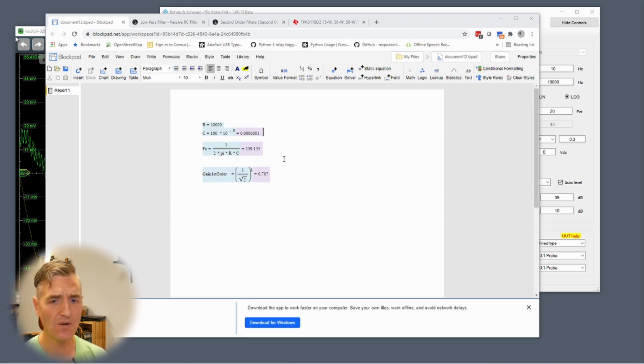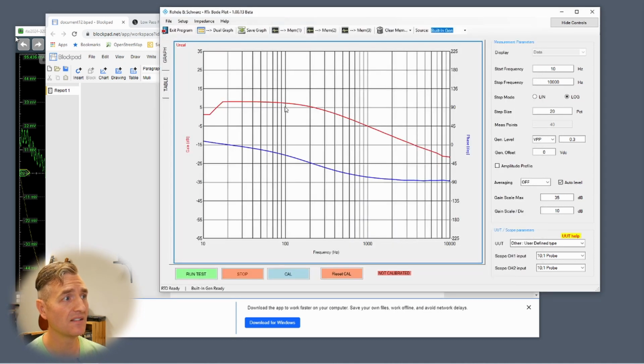And what I wanted to do today, so we were talking about a first order filter. So this is just one R and one C makes a first order filter. What does that mean? That means that this slope right here where the signal rolls off, it rolls off at 20 dB per decade. So from 100 hertz to 1000 hertz, it would drop about 20 dB if it's on its regular slope, and you can see it's continuing down.